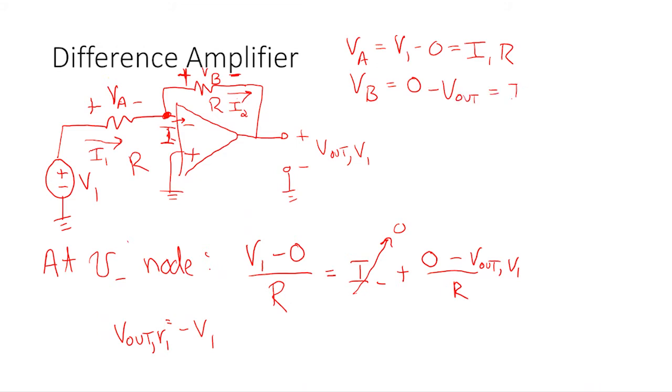And that's equal to I2 times R, like that. That's my way of doing it. And then I do currents in equal currents out. So it doesn't matter which of the plus and minus is first on that voltage source. What matters is that I write down my Ohm's law consistent with the passive sign convention, and that I write my KCL consistent with the directions of my currents.